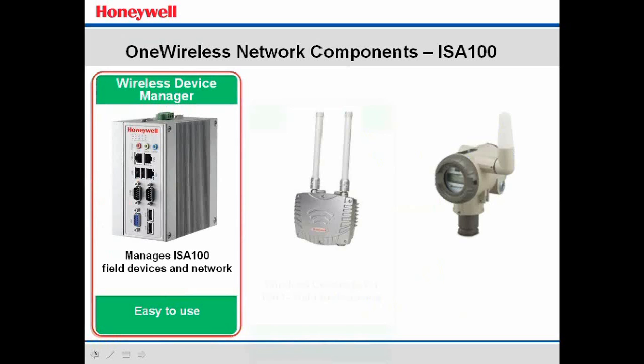But what the ISA chose to do was make it a little different. We have what's called duocasting. And what duocasting means is every device that you see in that example that has two paths is sending its data out both of those paths at the same time. Meaning they're in dual path formation, it doesn't form in the sense of a primary and a secondary where there has to be a failover in the event of a failure. In the event of a failure in this system, the data was already flowing another path anyway, so there is no failover. It just continues to flow as normal.